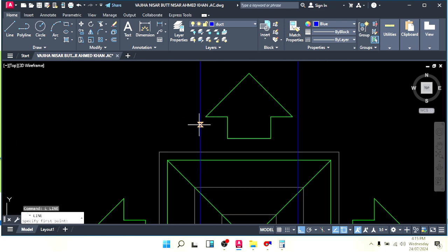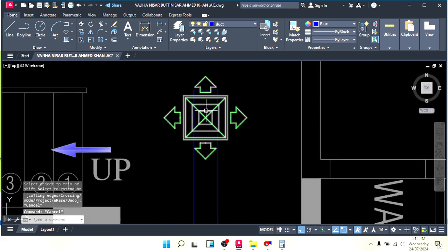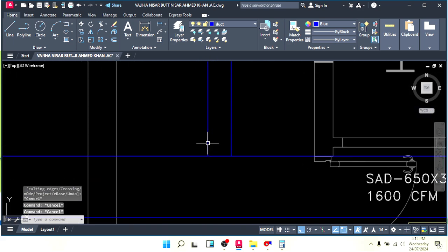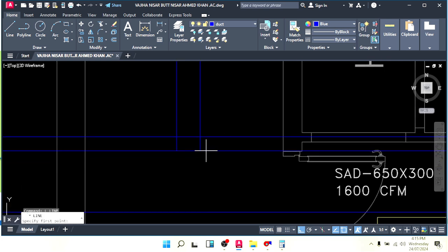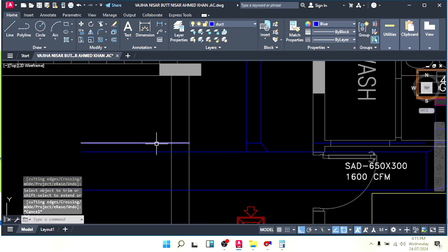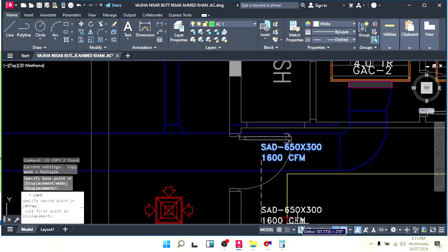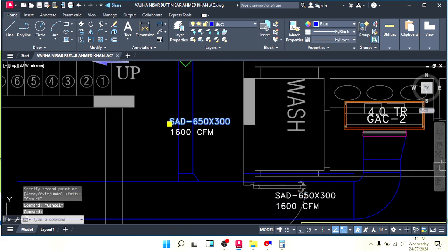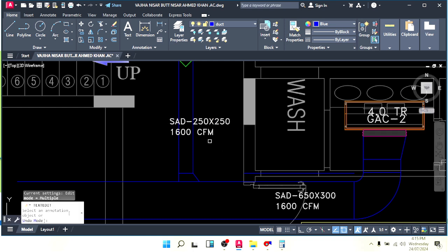like this and close here, and then we will make a plenum here, and we will connect this diffuser. Okay, make offset 15 cm here, make a neck for this one. We need a VCD also, that I will install later here. Okay, so write the duct size also here. This is 250 by 250, or 25 centimeter by 25 centimeter.